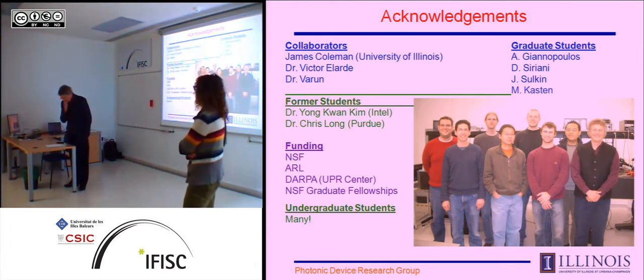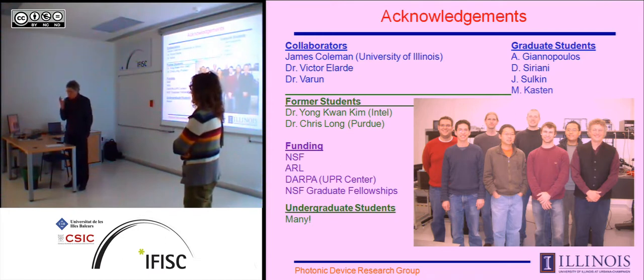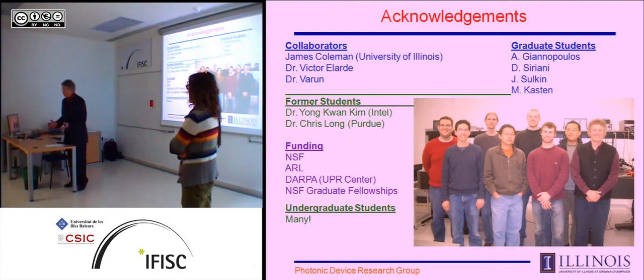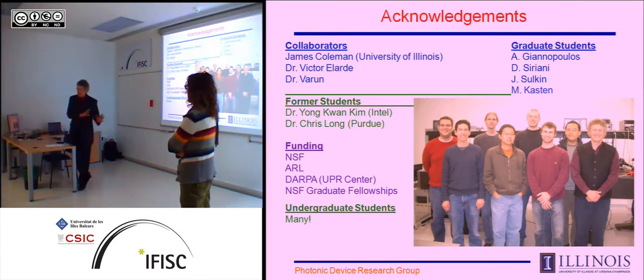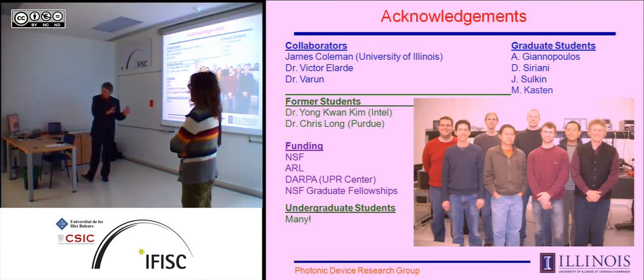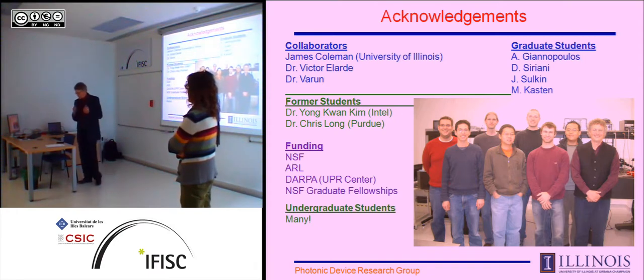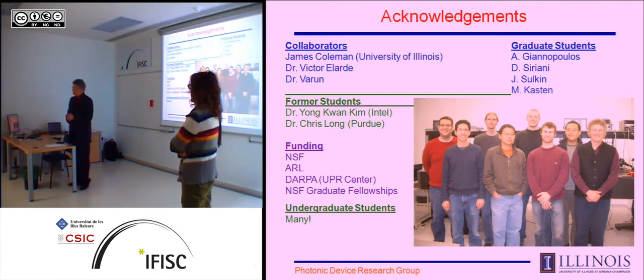What we've done is we've tried to identify the mechanism, and I mentioned that we believe we're injecting carriers and doing a carrier-induced change in refractive index. We haven't built devices where we can do things dynamically, but we can pulse the laser. And comparing CW versus pulse, what we find is it's not a thermal effect. It's not due to changes of temperature, which would give you a change in refractive index.